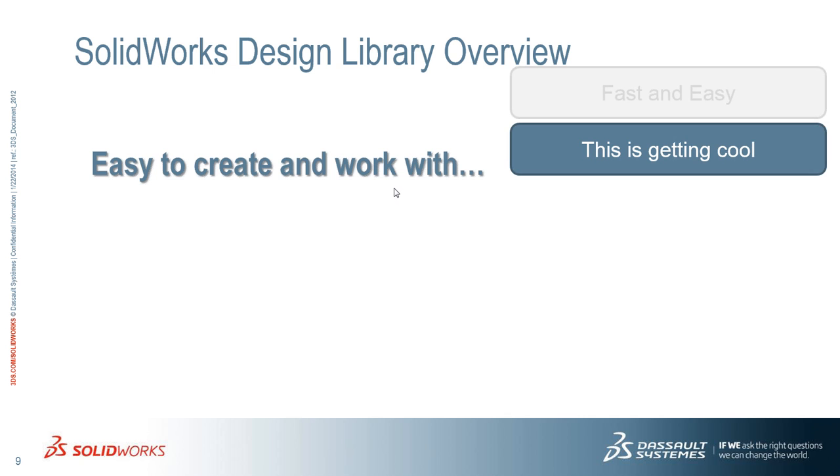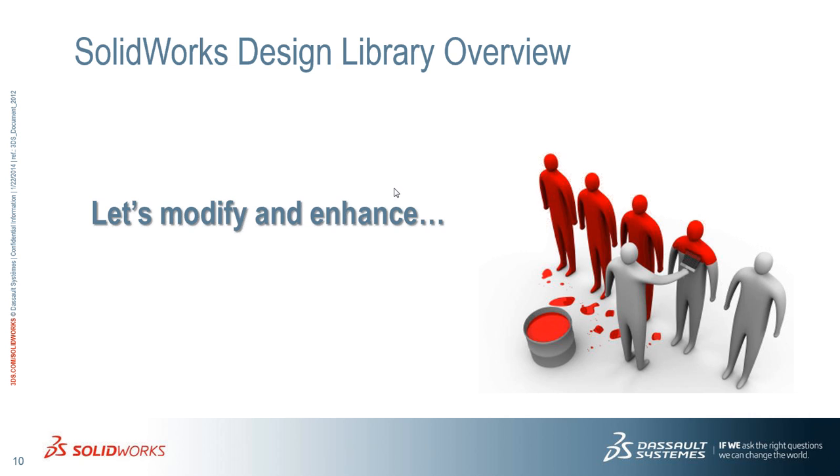If you haven't touched the library feature before, then you have just been exposed to a way that you can model very quickly the standard features that you have. Now, when you get into this kind of stuff, you maybe have some other features where you want to put a little bit more thought behind it and maybe control where the features get located, maybe not just on circles, but actually also with edges. And we can control that in here.